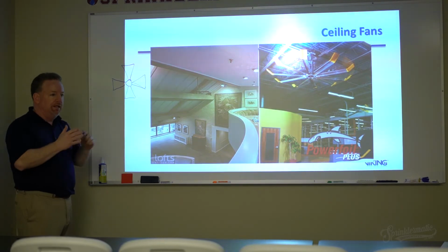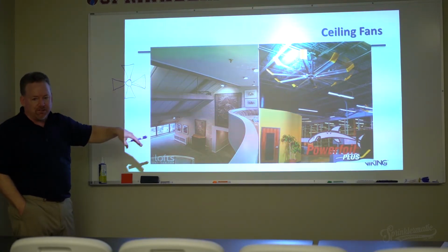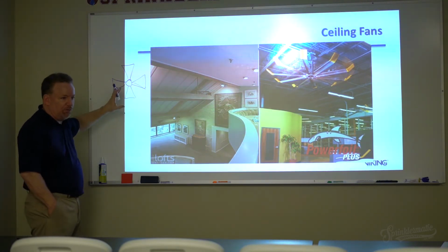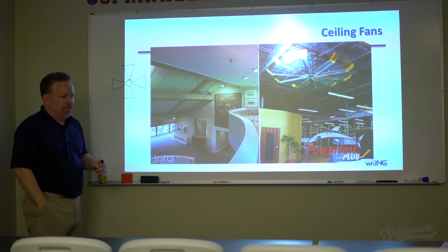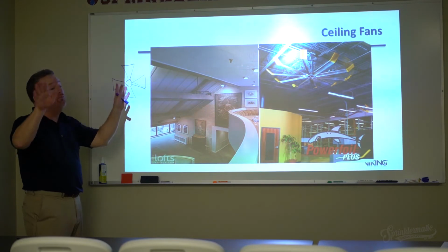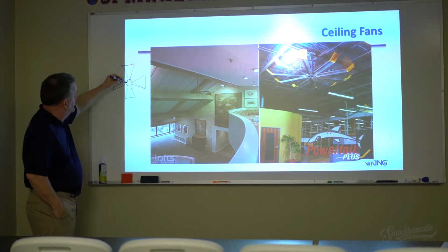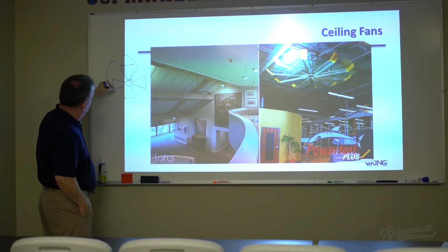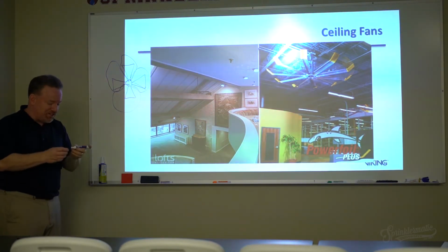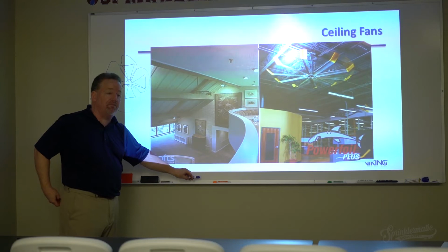But what happens when we put these in a restaurant, and it's Joe's restaurant, just regular standard old bar fare, and we've got the ceiling fans and they're all set fine, they're all great. All right, and then Joe's goes out of business, and in comes the tiki bar. And the tiki bar wants a whole new motif. And so what do they do with the ceiling fans? Ever seen these? Put the palm fronds on that overlap each other like that. What have they just done? They've just created an obstruction to my spray pattern that didn't exist there before.